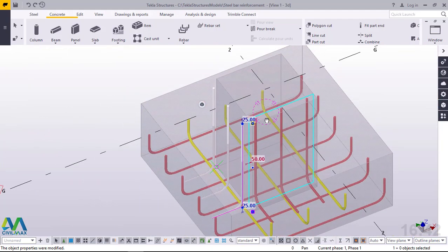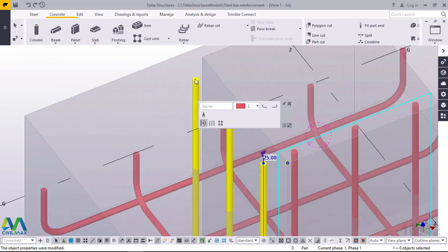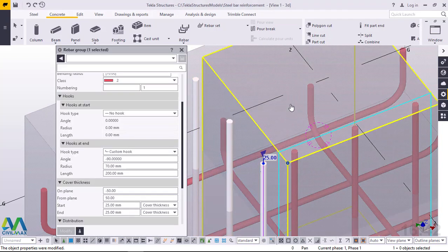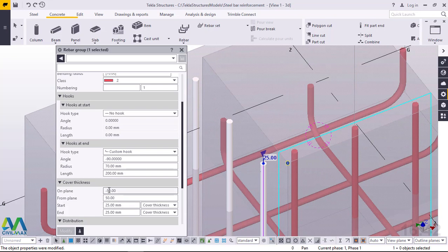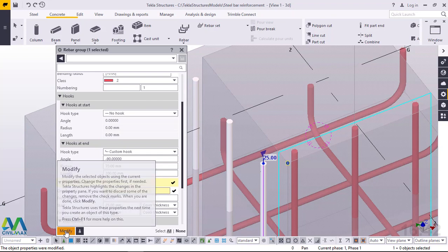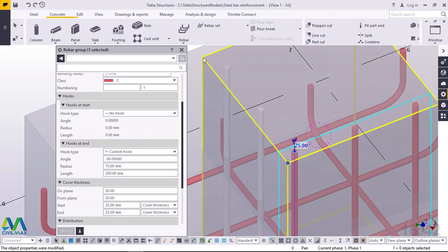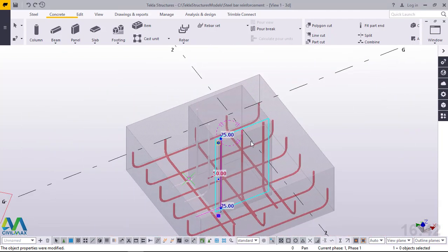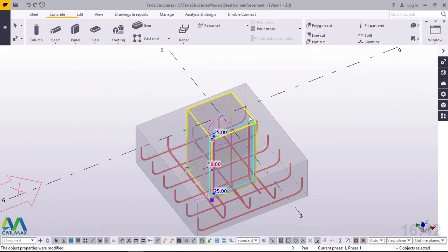Now the next step is just to ensure all the steel are located inside the reinforced concrete. I'll double click and come to this end, and I'll remove this, a negative prefix, to ensure all the steel are placed inside the reinforced concrete. Now I want to mirror this to this end, but what I must put into consideration is the placement of my XYZ axis.